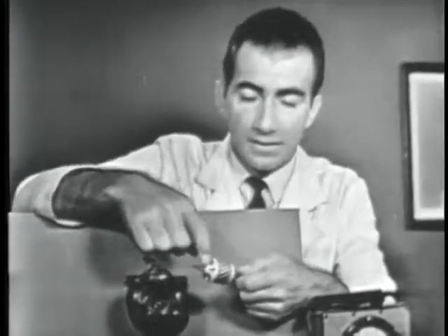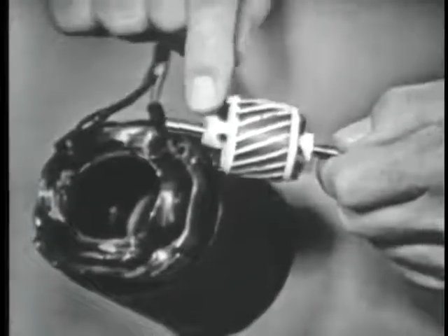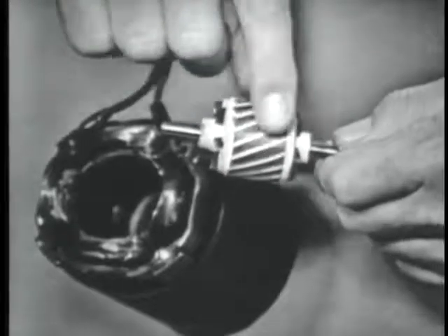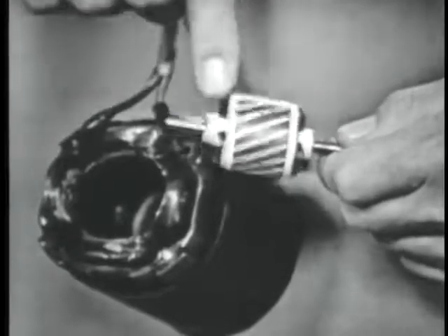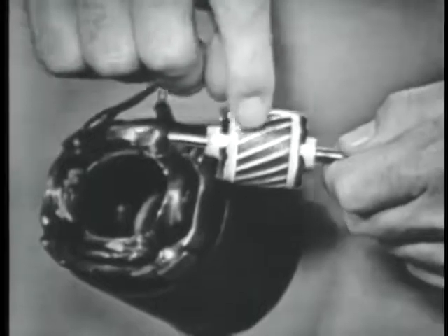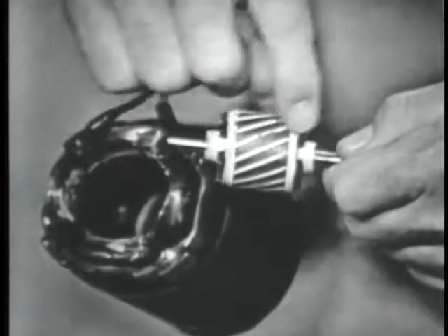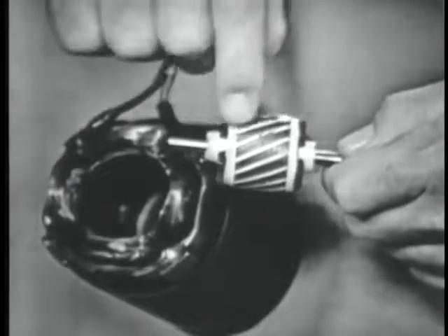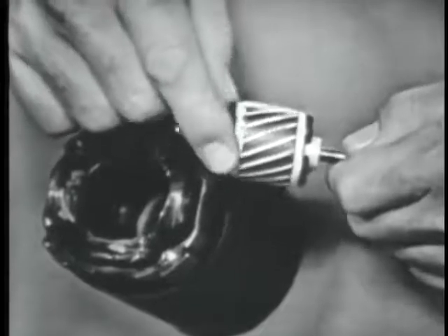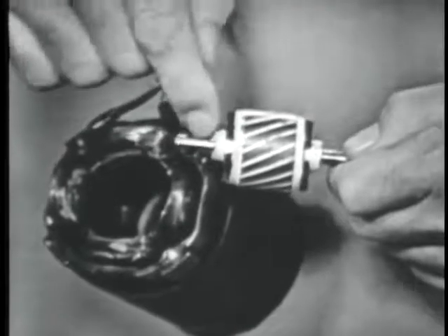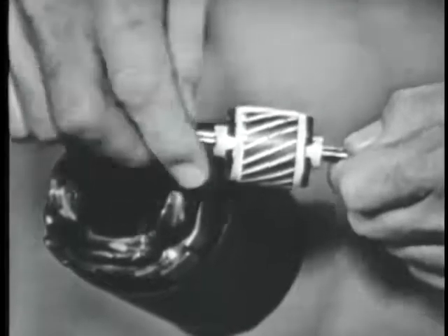Now actually, the rotor is the same thing, or almost the same thing. And a rotor is made in a very, very similar way. Instead of using windings of wire, however, we use a conducting ring on this end, a conducting ring on this end, and they're joined together by conducting bars, these little white lines. And the reason I say conducting, sometimes they're made of copper, sometimes aluminum. This one happens to be aluminum.